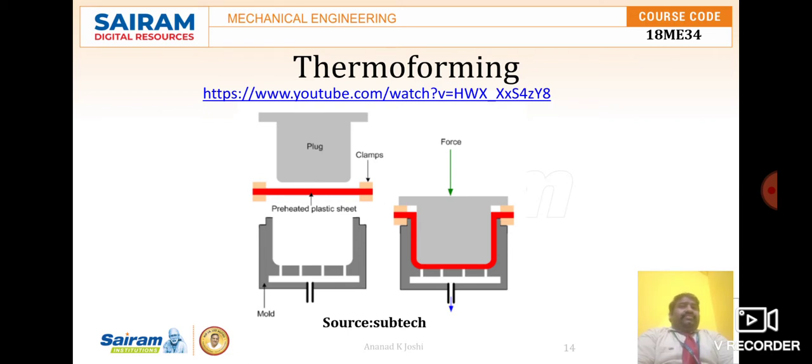Here in this figure you can see one of the thermoforming setups. It shows the various thermoforming processes available in the industry: vacuum type and pressure type. This is general mechanical thermoforming. In vacuum thermoforming, the plastic sheet is clamped to a frame and uniformly heated to make it soft and flowable. Vacuum is then applied through small holes in the die, which is positioned below the frame.